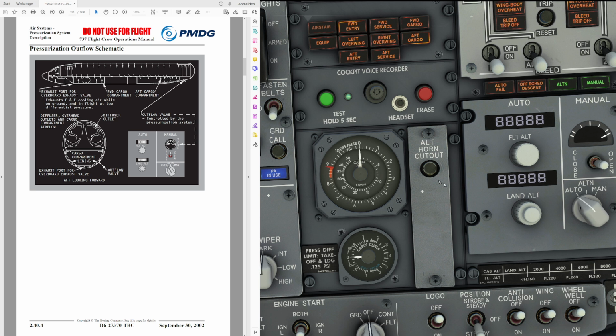So now, while the crew has been descending, which of course took a couple minutes to get down to 10,000 feet, the cabin has actually been pressurizing again. And it's been pressurizing so quickly that by the time they reached 10,000 feet, the cabin altitude was actually below sea level, so the needle was anywhere here in the region of 37,000 feet on the indicator, while the actual cabin altitude was anywhere like 4,000 feet below sea level, if I remember correctly. And this led the crew to believe that the cabin altitude was still at 37,000 feet,